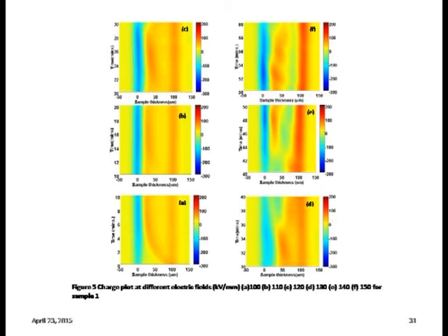You can see this charge is accumulating just adjacent to this electrode, but it is not merging with this even after 30 minutes also. And here different kinds of charge formation you can see. Here positive charge and negative charge and positive charge, like this. So different kinds of space charges for different fields: this is for A 100 kilovolt per mm, B 110 kilovolts per mm, etc. I am sorry, we have increased the voltage actually, 100, 110, but the time is continuous.